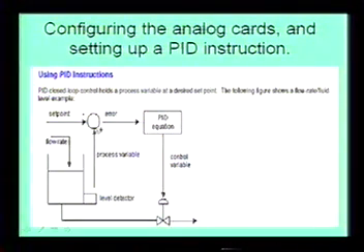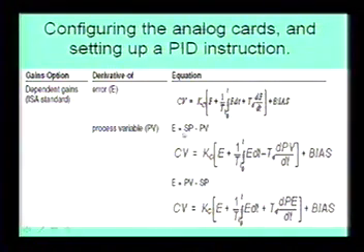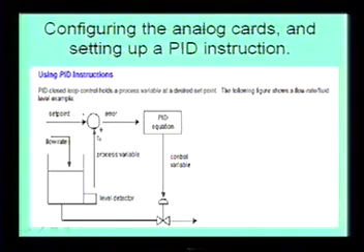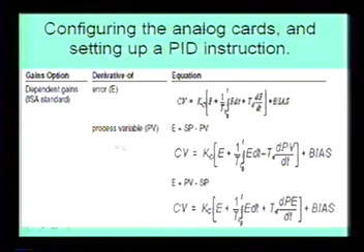And then if you have E equals PV minus SP, remember right here I said this is minus plus, this could be plus minus. So here's set point minus process variable, or process variable minus set point. If you change the controller to this, you're actually changing this right here. So you can see it's the same formula, but you've changed the sign on your process variable here.